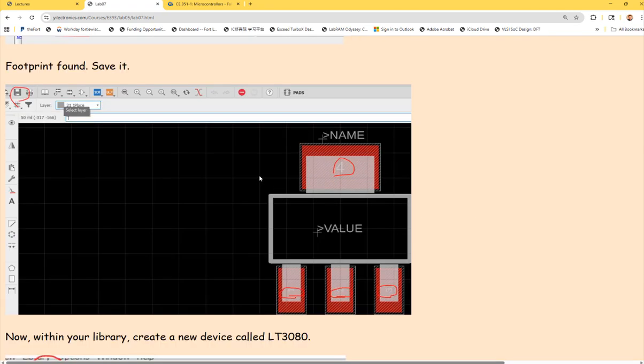So if you have this package or footprint available in the library, you could reuse it. Just create a different symbol and assemble it into a different device and rename it. So it becomes available in your library. Another way, for example, if you don't have it in any of the libraries, you download it and install it to Eagle, or you don't have any symbol for it.